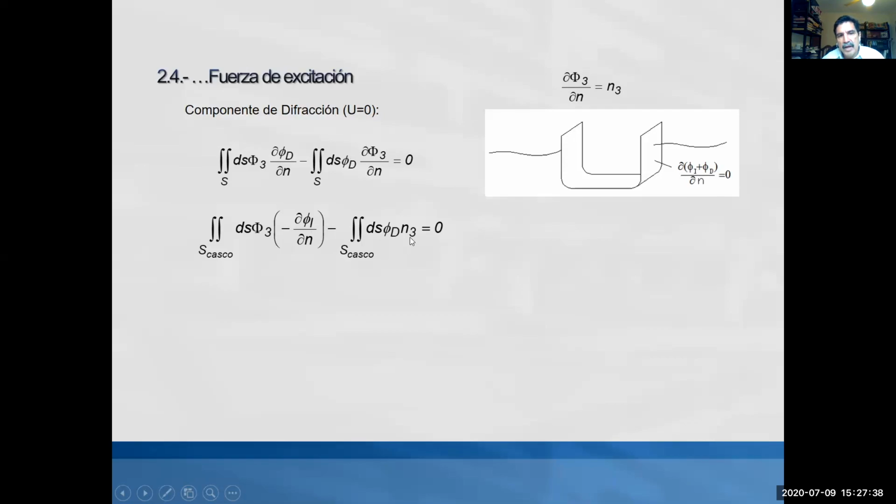Okay, and we can recognize that on this side, we are very close to evaluating the force per unit length on the ship because of the diffraction. And that term is equal to this one here. And this is the incident wave, which we know. And this is phi3, and this phi3 has already been solved. So we can express this as a function of something that we know. So this is really clever. It was really clever. Okay, so this is our expression.